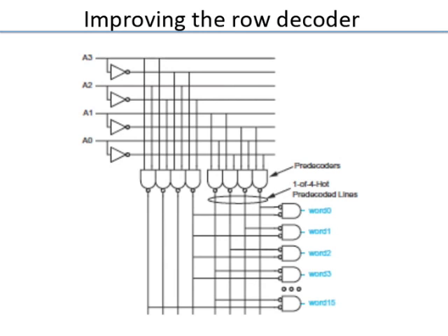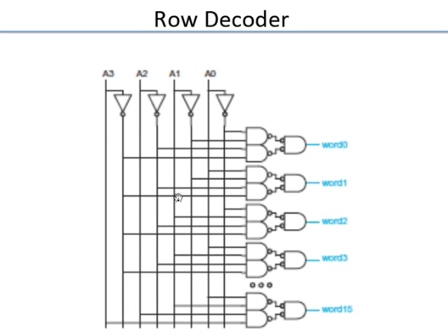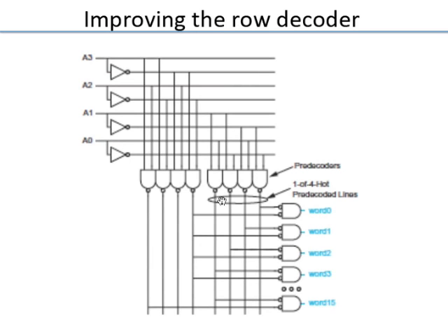Mainly because if you go back out here you have very long wires, and no matter what the address bits are, you'll always have 4 long wires switching, because for each address bit one of these 2 will switch from 0 to 1, again same here. Whereas here, because you did the pre-decoding, of these long wires, only one of these 4 will switch and one of these 4 will switch. You'll have only 2 wires switching. So activity is reduced on these long wires. So pre-decoding is the preferred option. Turns out even for speed it's better. Power also it is good.